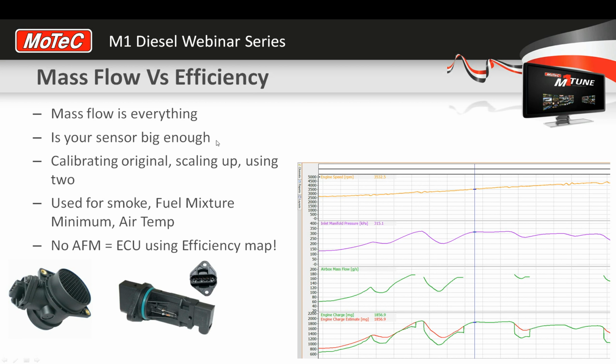My rule at the beginning of this path is basically if you're running, or intend to run, any more than 30 or 40% more airflow or more power than what the stock engine has been set up to run, then the stock mass flow meter is potentially going to be running out. It's pretty similar to petrol engines, to be honest. So your average petrol turbo car was probably running out around 20 or 30% more power or more boost. You probably talked about that in those days.